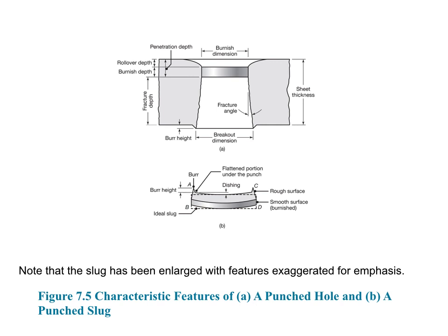In the case of the hole, this area is on the upper region, since it rubs against the punch. However, in case of a slug, this region is on the lower side. This is because the area has rubbed against the die wall. It is important to remember that the ratio of the burnished to rough area on the sheared surface increases with increase in sheet thickness and clearance, and decreases with decrease in sheet thickness and clearance.